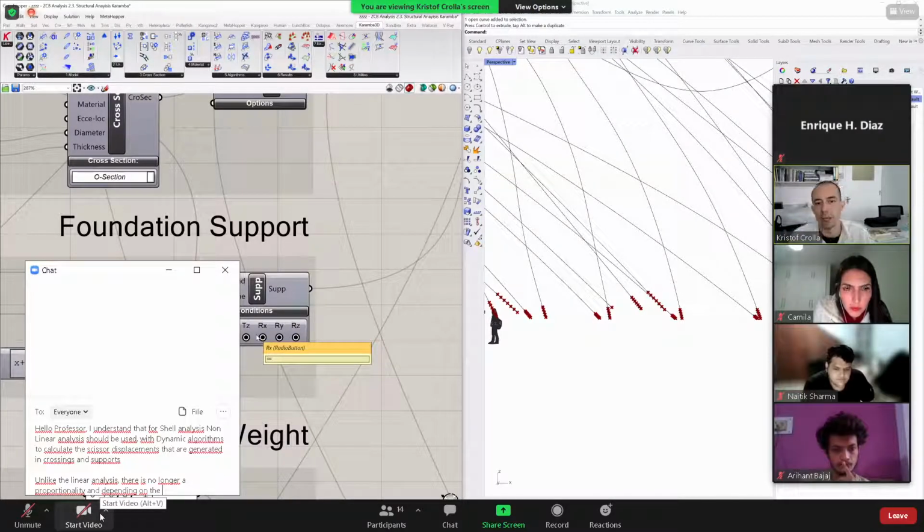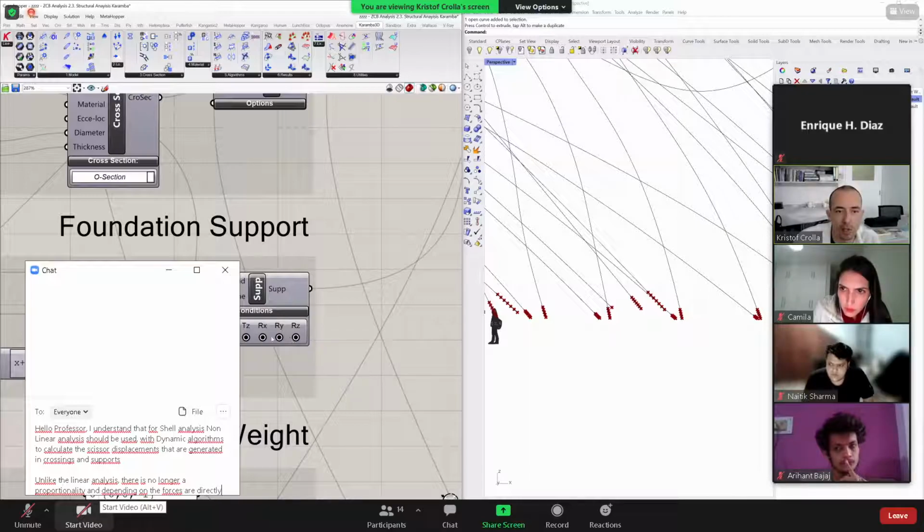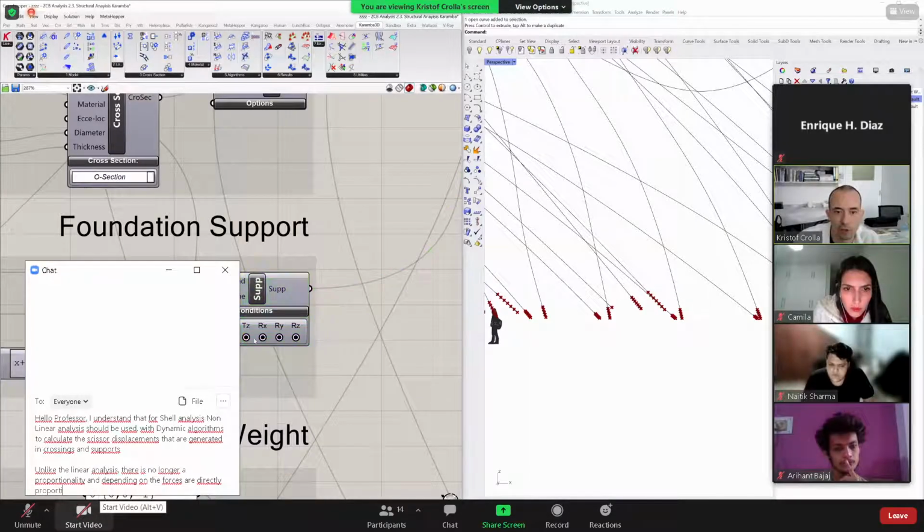As I showed you on Monday, our columns are slid over a rebar. So that means that they can definitely not move around in the X, Y, Z direction on the ground. But that rebar actually also locks them into a rotation around all of these axes. If you want to have a hinge on the ground, then you just need to switch off your rotations here. I shouldn't do it because the calculation might take some time. You just switch off your rotations here, and then you basically have a hinging connection on the ground.